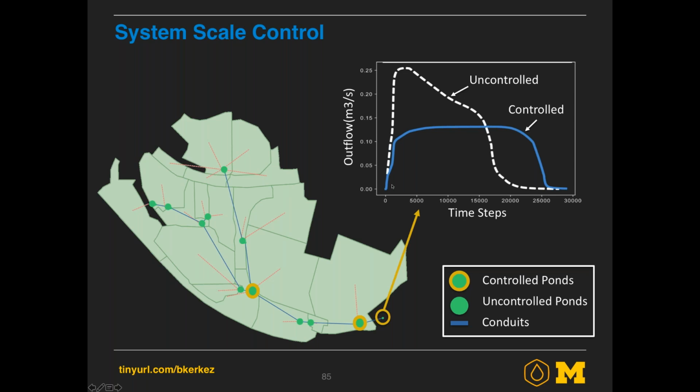And these tabletop shapes are cool ecologically because we know, for example, in our watershed, if you keep it really flat and you don't exceed a critical threshold, you might not stir up sediments. There's a geomorphically significant threshold that's not going to tear up the stream. So if we know that about our watershed, we can just hand that over to the control algorithm and say, make sure it doesn't exceed that value. So basically we're starting to create hydrographs of arbitrary shapes. And so that's one way to do it.